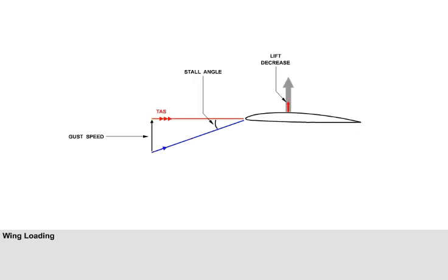We have seen that a gust can increase the load factor and bend the wing, but it could stall the wing instead, in which case lift will decrease. There is thus a minimum speed at which it is safe to fly in turbulence to avoid a stall, and a maximum speed to fly in turbulence to avoid overstressing the structure. To provide a speed margin from both these eventualities when flying in turbulence, the rough airspeed, VRA, is used, which we will examine in detail next.